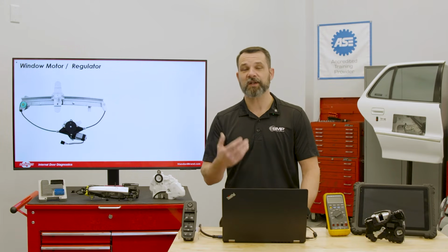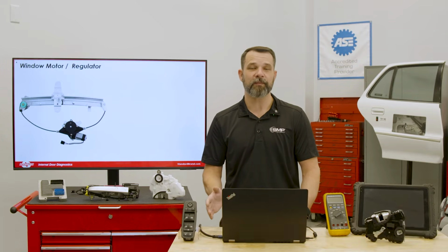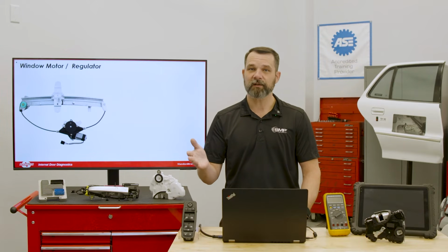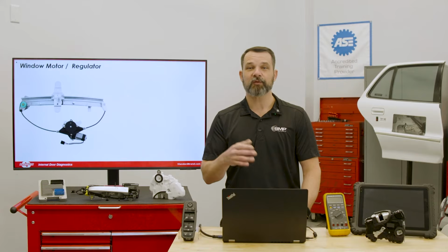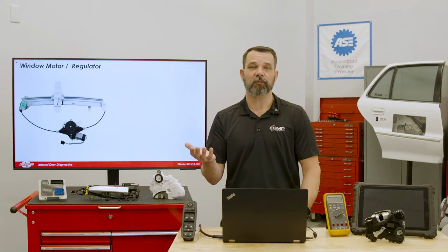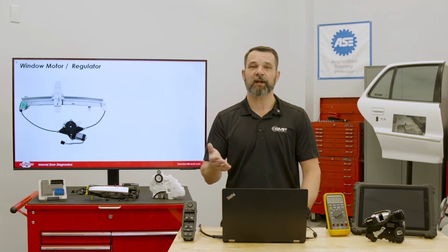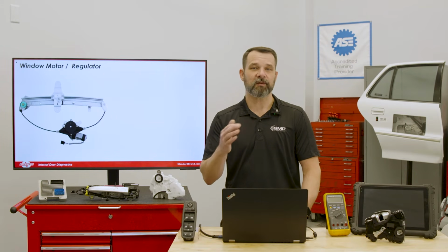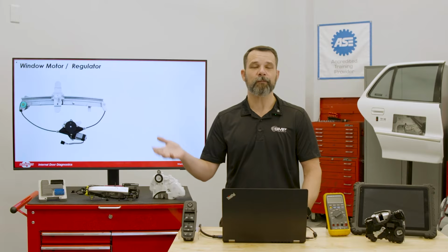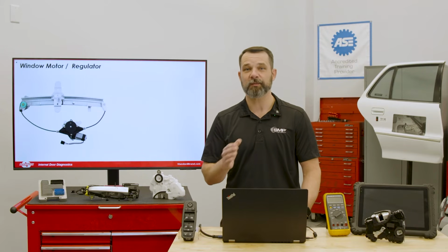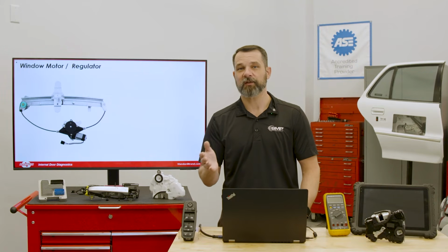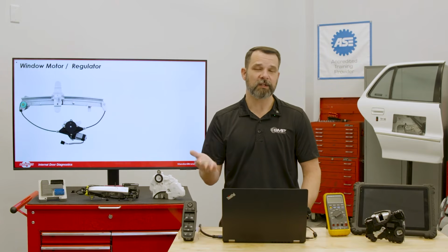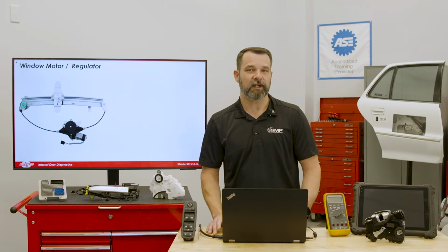So moving on, we now have the power window motor, right? And this is really just another reversible DC motor. It's usually driving a cable regulator or a scissor regulator to raise and lower the glass, and they're controlled by switches or, again, automatic up-down smart modules. Now, the polarity of power delivered to the window motor is going to be determined by the direction, right? So positive, negative is going to make it go up. Negative, positive is going to make it go down.